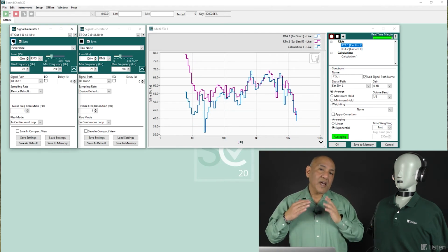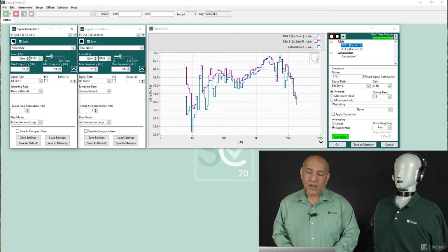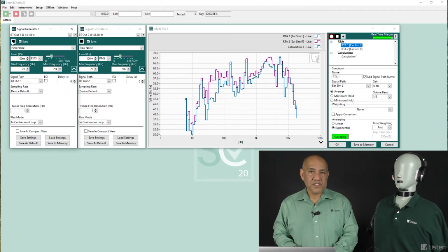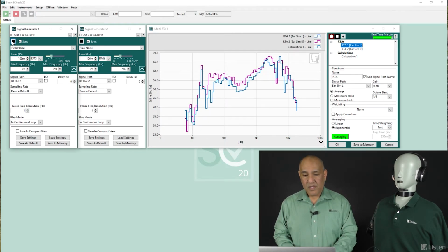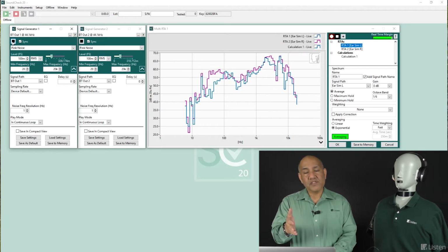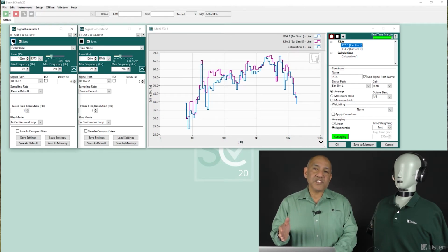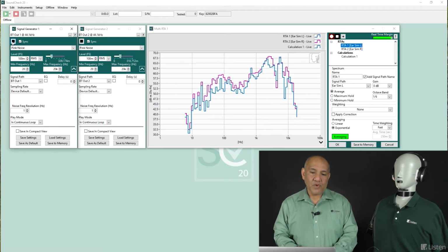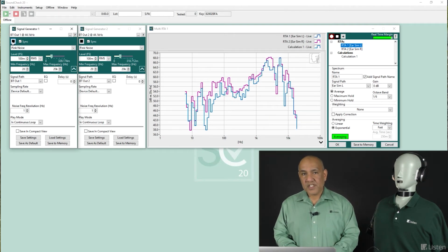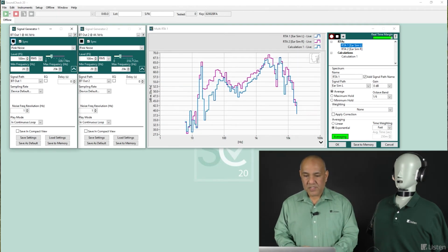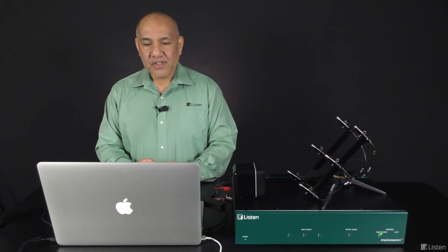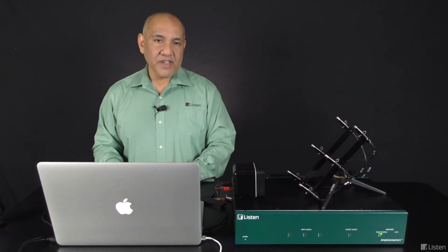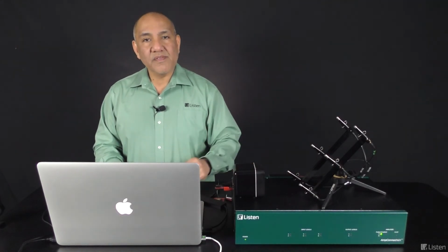Practical use, once I have a good balance of the left and right ears, then I can close this instrument and perform a sequence that measures the headphone. Okay, so that is using a virtual instrument configuration, multi-channel RTA, feedback in real time, 2 synchronized signal generators generating pink noise. Next, I'd like to demonstrate the practical use of using the multi-channel RTA measuring input from a 6